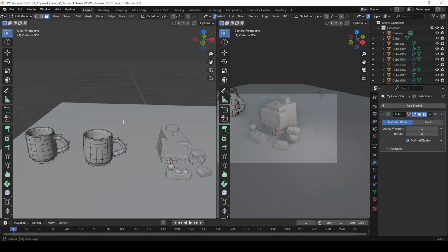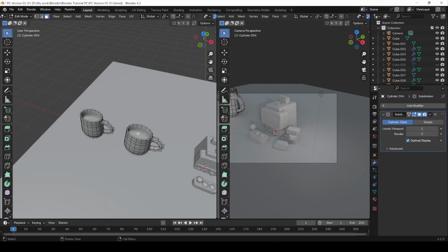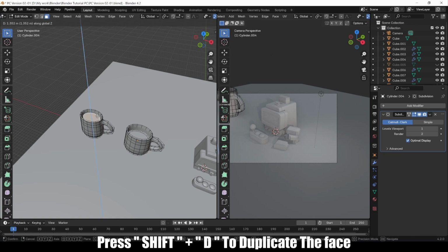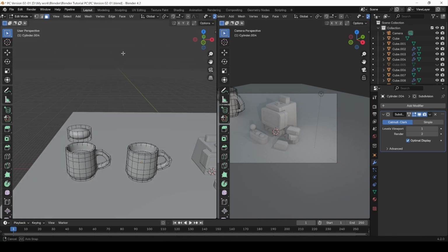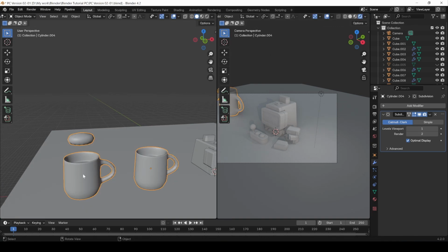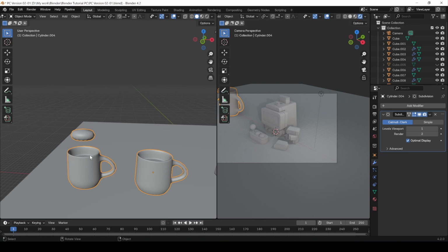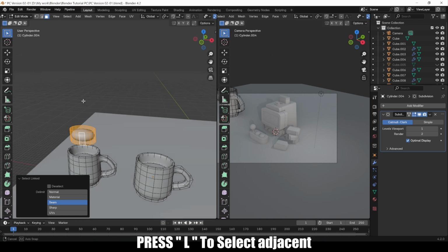Actually now you have merged these 2 objects, now they are the same, but let's say you want to separate some edges or some shapes. Let's say you created this face and you get it up and then you extruded this to get some shape, and then you want to separate this object and you don't want this object to be part of this object. Then enter edit mode, select all the adjacent of this mesh, so press L to select them all.